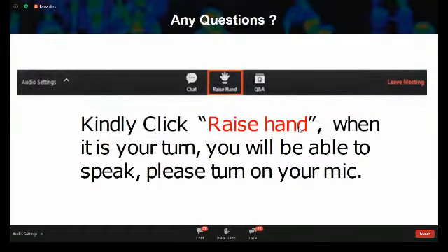Alhamdulillah, fine. Regarding the device, if I have an old device, maybe ZK or something, or any device we have at the customer, can this device support it together to take all the data or everything? Actually, we have the option to connect this device. If you have a ZK controller, then we have a Wiegand output from this device, which can be used to integrate with third-party controllers.